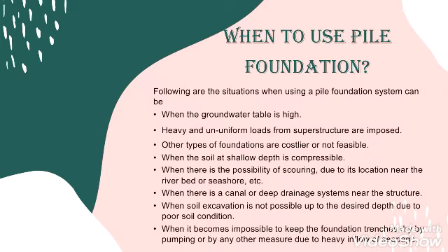When there is a canal or deep drainage system near the structure. When soil excavation is not possible up to the desired depth due to poor soil condition. And last is when it becomes impossible to keep the foundation trench dry by pumping or by any other measure due to heavy inflow of seepage.